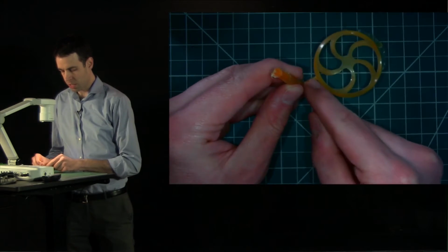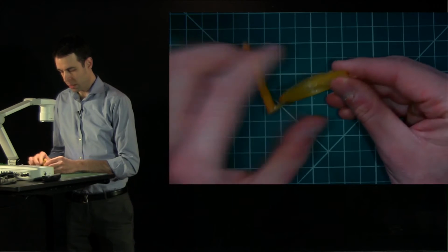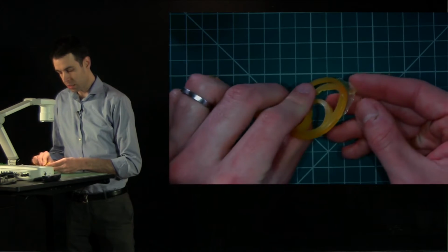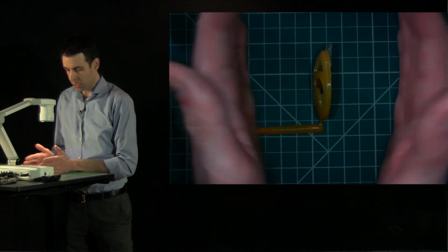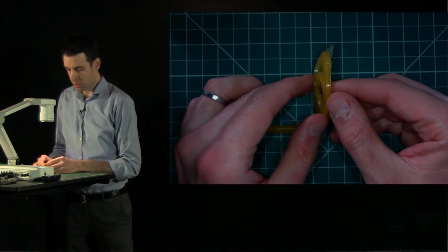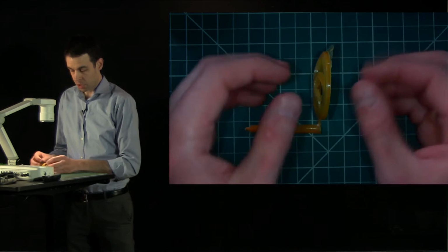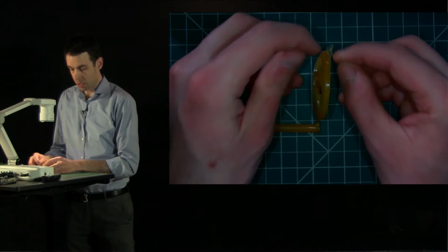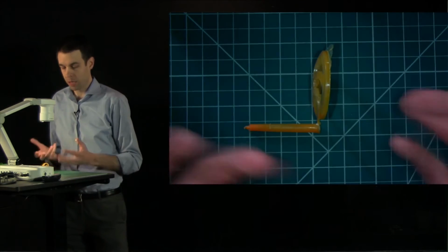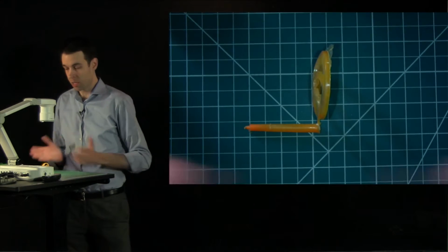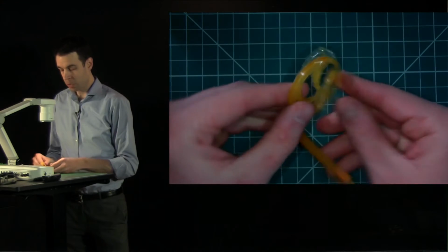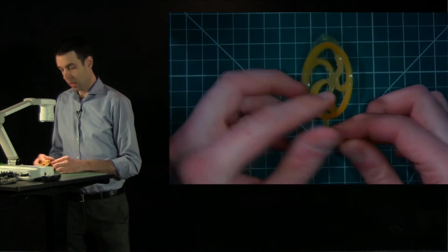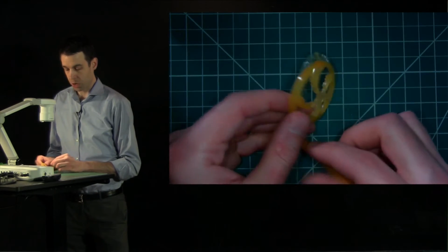Plastic is injected from this side, flows around the periphery, and flash exists here because the pressure is too high or because the mold halves that open and close like so aren't precisely machined or aligned such that the plastic cannot flow into the gap defined by the parting line. And we need a parting line so you can take the molds apart cleanly in two halves, but the parting line can't be too big or non-uniform such that flash is generated.